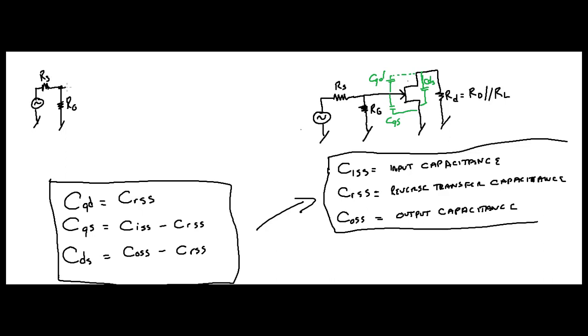Now, what else you think we're going to have here? We're going to have a capacitance, this is going to be CGS, your gate source, right? Now, remember your buddy Miller? There's a Miller capacitance here. This was discussed in the bipolar junction transistor high frequency response video. Miller capacitance, this is what I'm talking about.